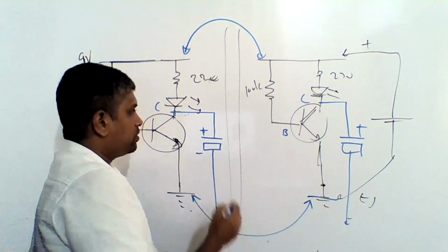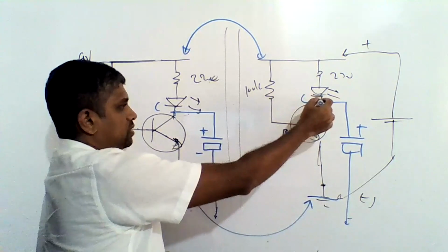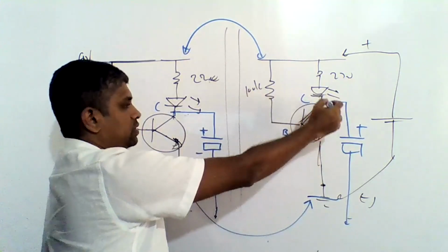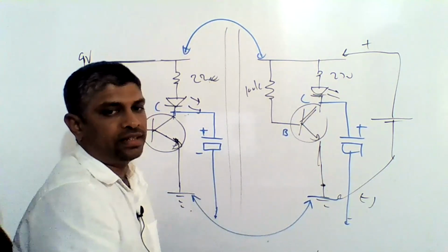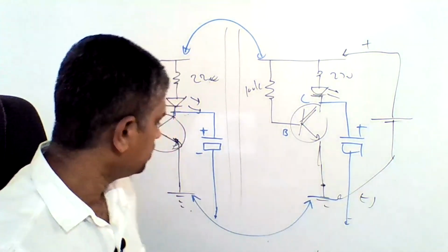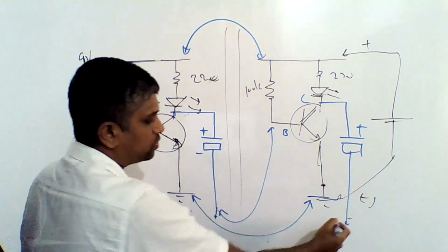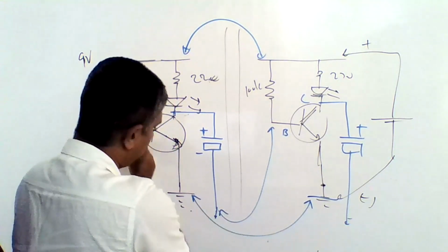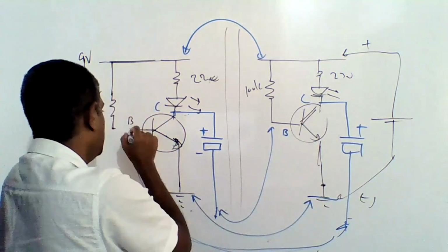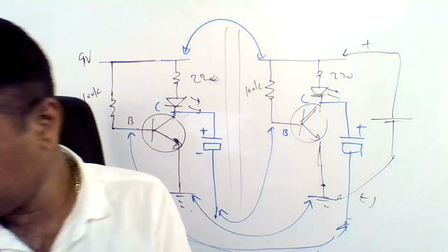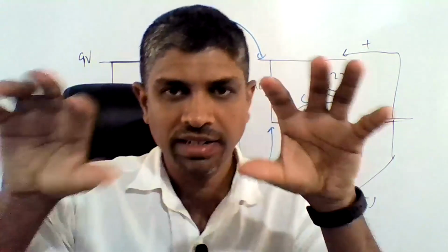So normally what you can do is connect the positive terminal of the capacitor to the collector, and connect the negative terminal to one of the three rows available. Through a jumper wire, you can connect this negative terminal of the capacitor with the base terminal. If you do this carefully, only then can you see the multivibrator circuit.